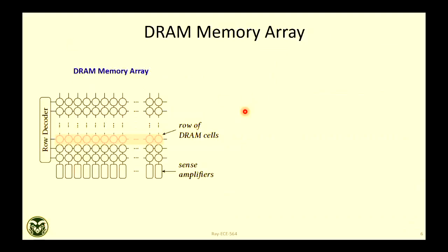So just quickly recall, this is how your DRAM array looks like. It has a row decoder, which will select a particular row, right? And this column decoder, where a particular column address will be selected. This is the bitline direction, vertical. Data from this row will come to the data buffer through a sense amplifier. The sense amplifier will sense when you activate the bitline. Based on the data, the bitline voltage will go up or down, and then the sense amplifier will amplify that.